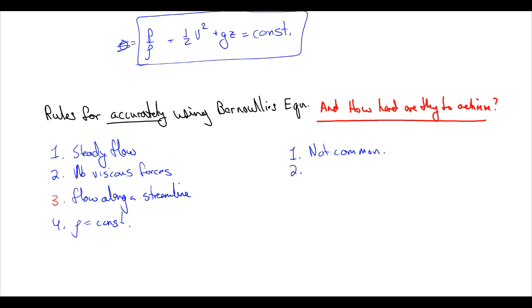But remember that tau, our shear stress, is equal to mu times the gradient of our velocity in the direction perpendicular to the velocity direction. So if we're looking at the u component of velocity, it'll be in the y direction, for example. And remember that this is velocity and this is distance. So if we want to reduce the effect of our shear stresses, we can just have slow velocities and large distances, right?